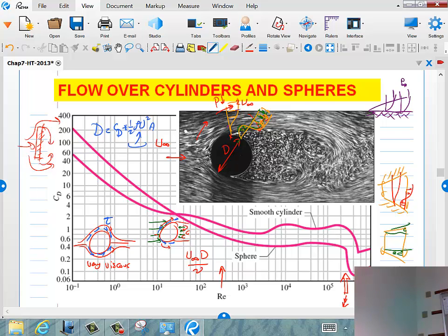But what happens is, basically the velocity is getting smaller and smaller. I'm not reading the velocity profile. Okay? So you can see how the velocity profile is very thin. It gets thinner and thinner because it's a boundary layer to start with. And on top of that, I'm telling you there is pressure. We call it adverse pressure gradient. When you're going this way, down the hill, kind of, the pressure actually increases.